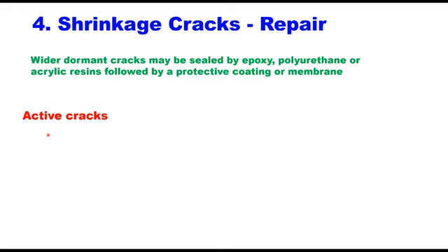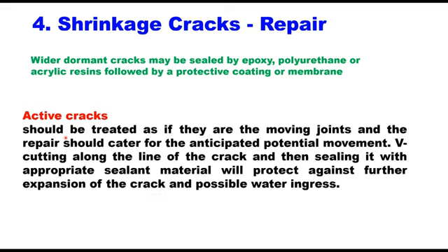Active cracks are those which grow with time, and the reasons for their growth may be either continuous foundation settlement, or sometimes the cracks start acting as contraction and expansion joint and open with time. These cracks should be treated as if they are moving joints, and the repair should cater for the anticipated potential movement of these cracks. V-cutting along the line of the crack and then sealing it with appropriate sealant material will protect against further expansion of the crack and possible water ingress.